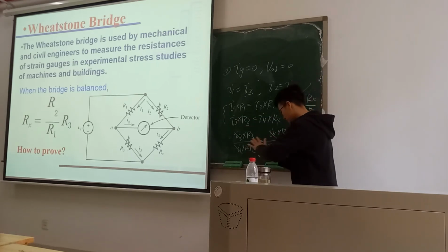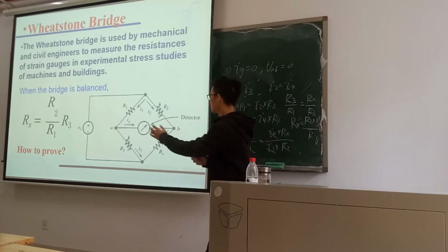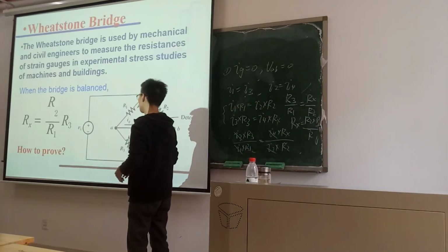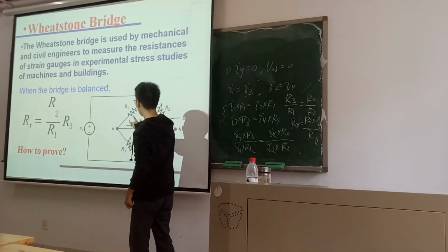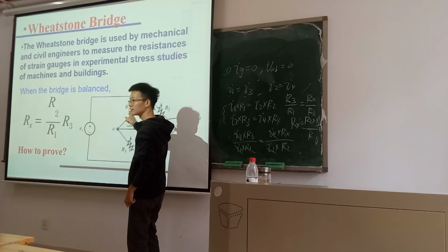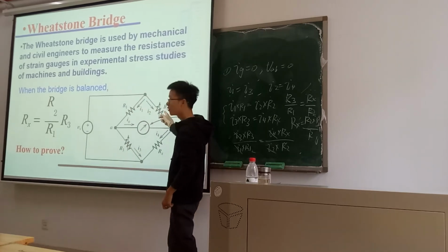So in your application, you just need to remember: Rx multiplied by R1 is equal to R3 multiplied by R2.